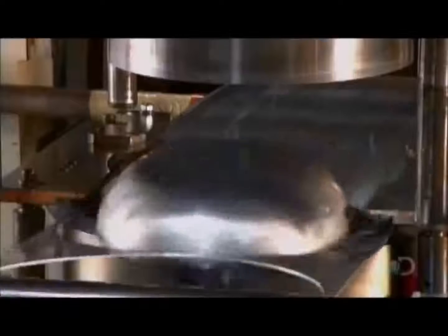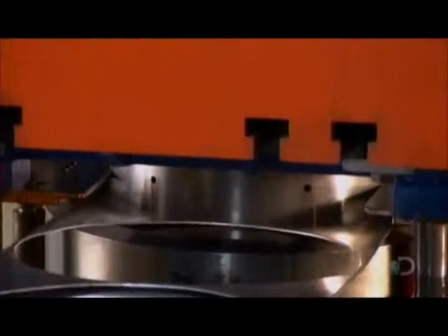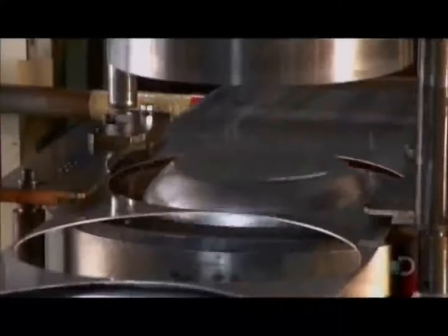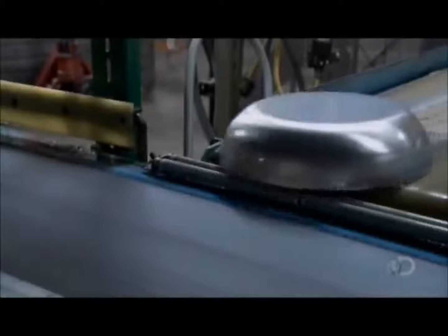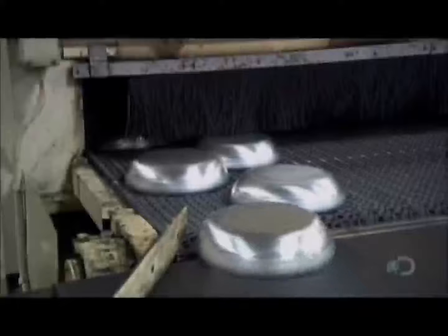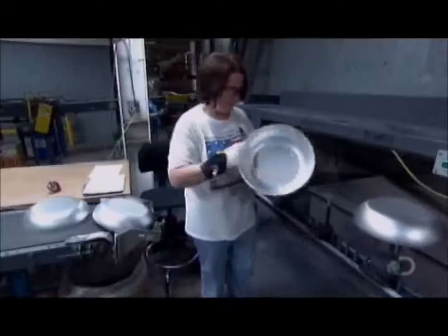The pressed aluminum, now in the shape of a pan, falls onto a conveyor belt. The leftover aluminum sheets are reused for the initial casting process. The pan then enters a washing station where it is cleaned and treated with sodium hydroxide. The sodium hydroxide opens up the pores of the aluminum so the enamel coating sticks outside and the non-stick finish adheres inside.